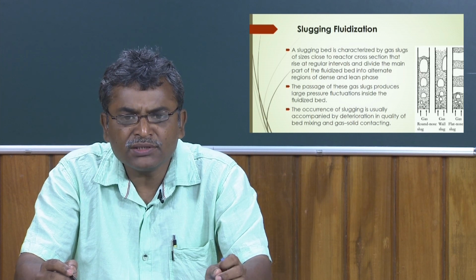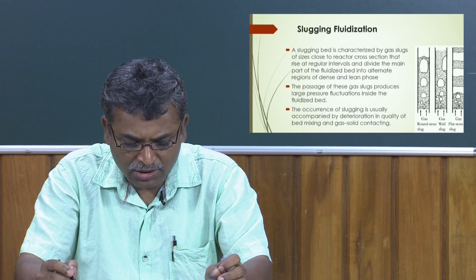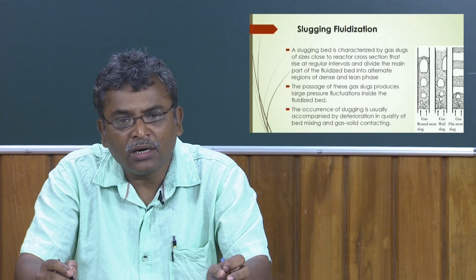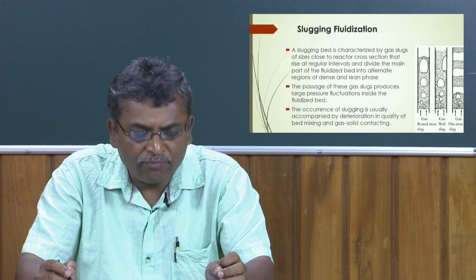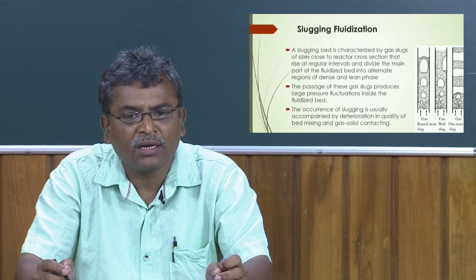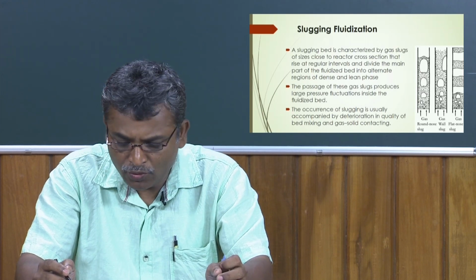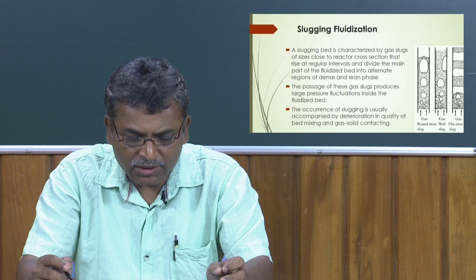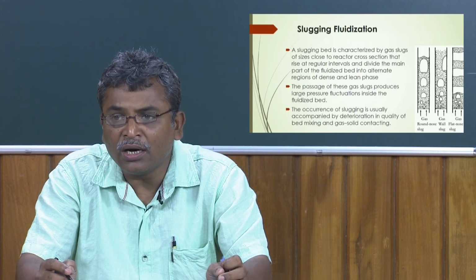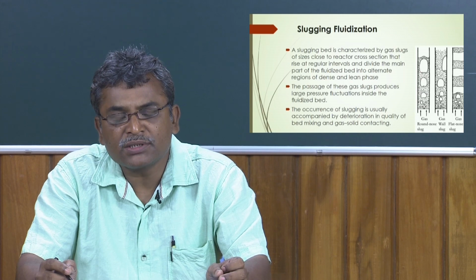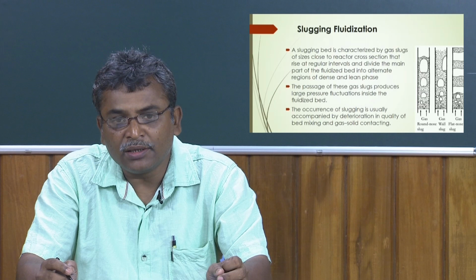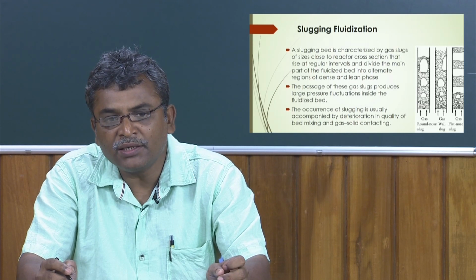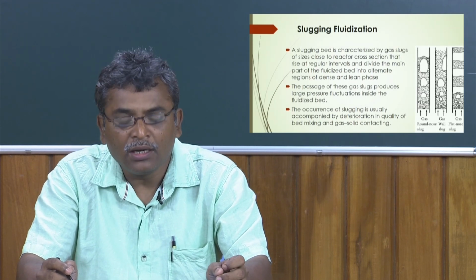The occurrence of slugging is usually accompanied by deterioration in the quality of bed mixing and gas-solid contacting. So this phenomenon will govern mass transport and even heat transport in the fluidized bed, if it is applied for a specific application.